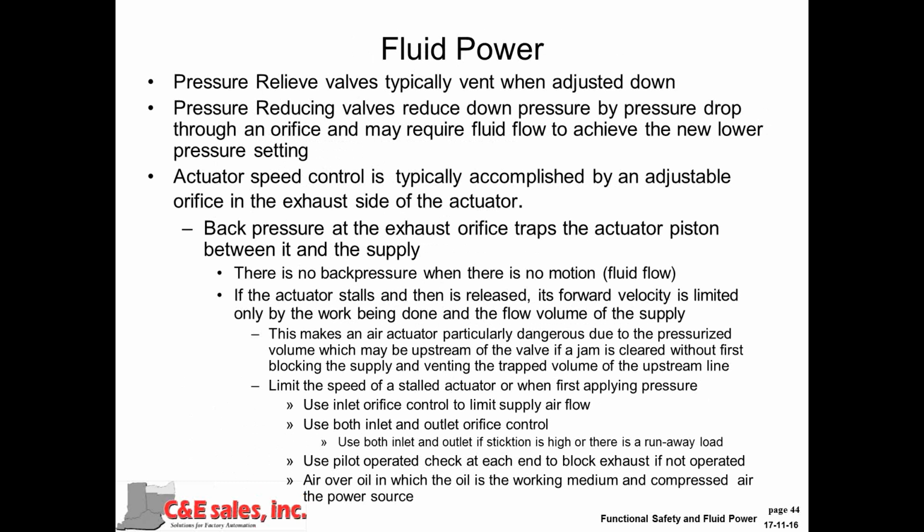I mentioned earlier the problem about air cylinders. Typically, we control the exhaust from that cylinder, which develops a back pressure on an orifice so that the cylinder can only move a certain speed.